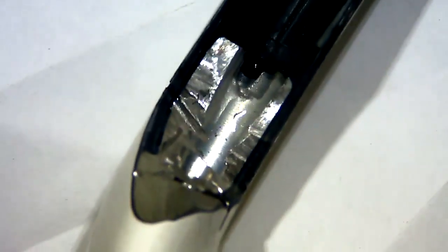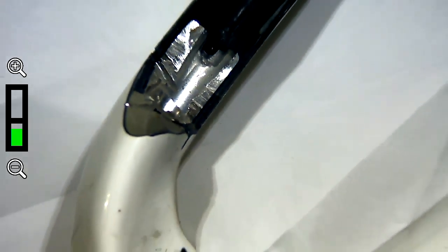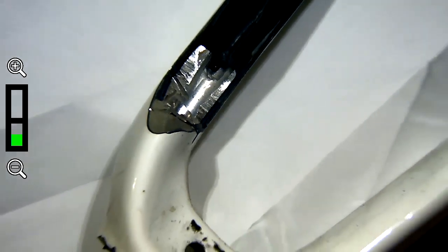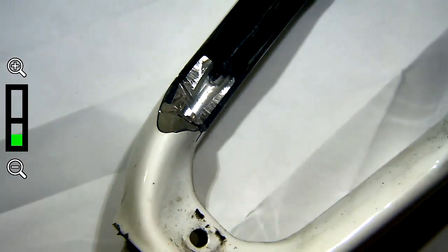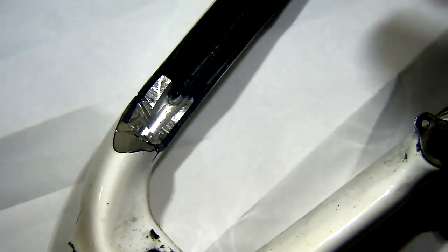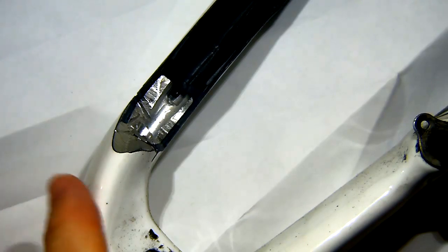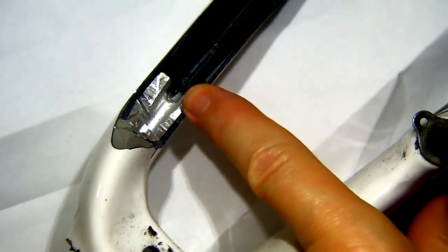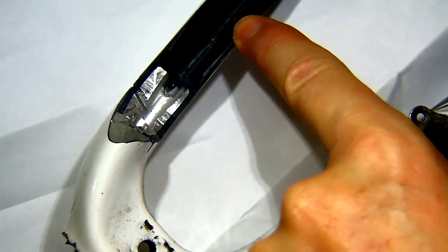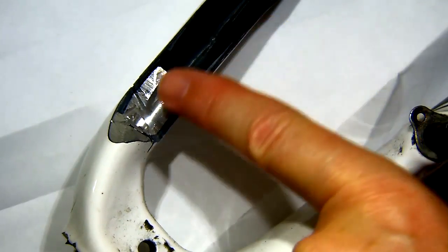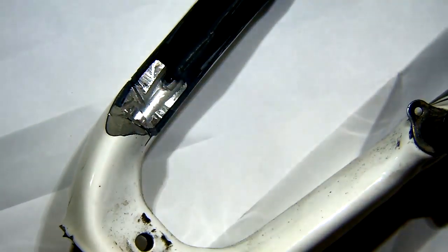Second issue is carbon fibre is great for certain things, glass fibre the same, but it doesn't have, let's call it Hertzian strength or contact strength. When we get to a point where we want to have a lot of stress going through the object through a small area or a small contact zone, we've got to have some way of interfacing our carbon fibre, because it doesn't have the advantage anymore, to a bit of, here we've got aluminium.